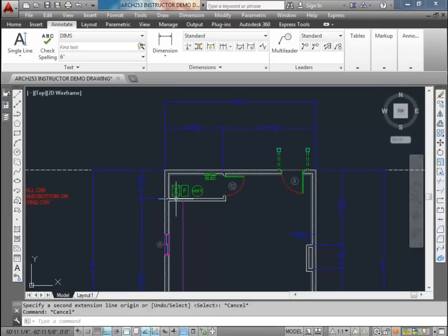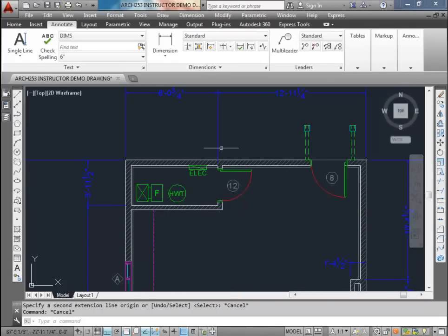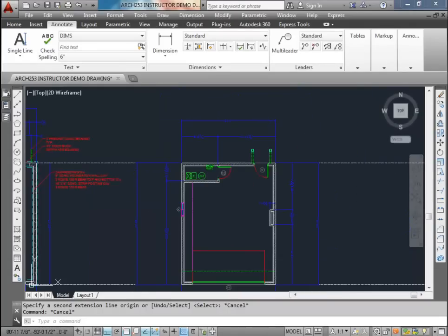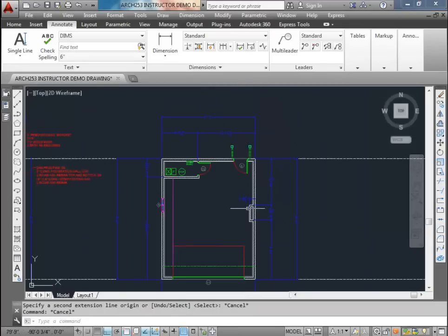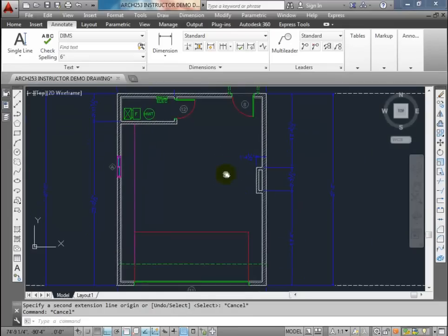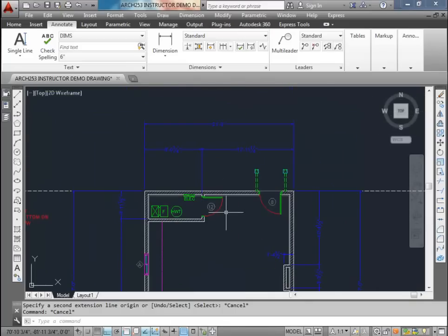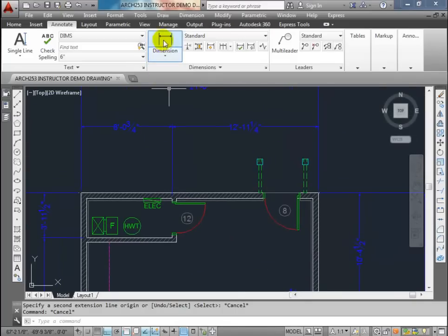Okay. Now I don't need to do any dimensioning for inside of the wall here because it's already dimensioned. We already have the location of the wall on the outside in relation to the exterior wall, and we already have the location of this wall on the outside in relation to the exterior wall as well. Same thing with this wall here. We have a dimension relation to the exterior of the inside wall as well as each individual wall that comes back. So I don't need to do any other dimensioning on the inside of that plan, which means it's free for notes and anything else that we need to add, which is our next step. Sorry, we need to dimension our openings first, but our next step after that will be the walls.